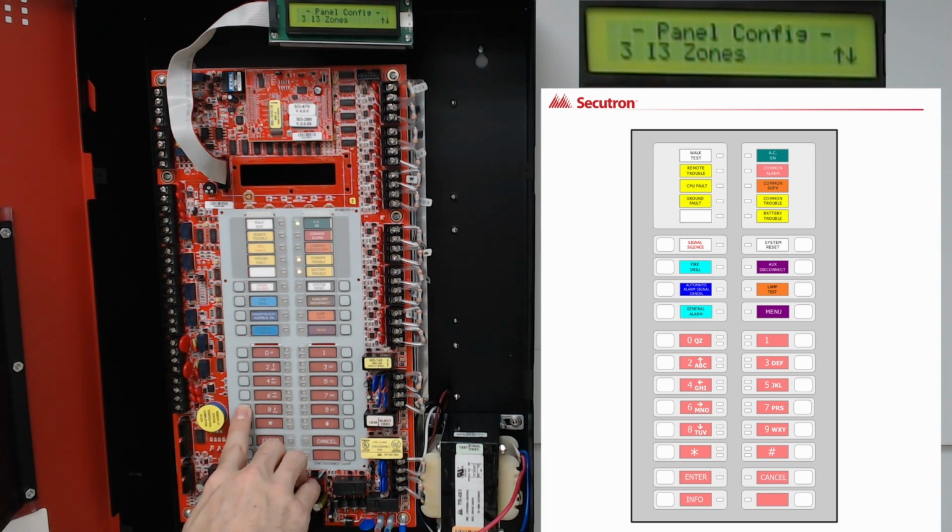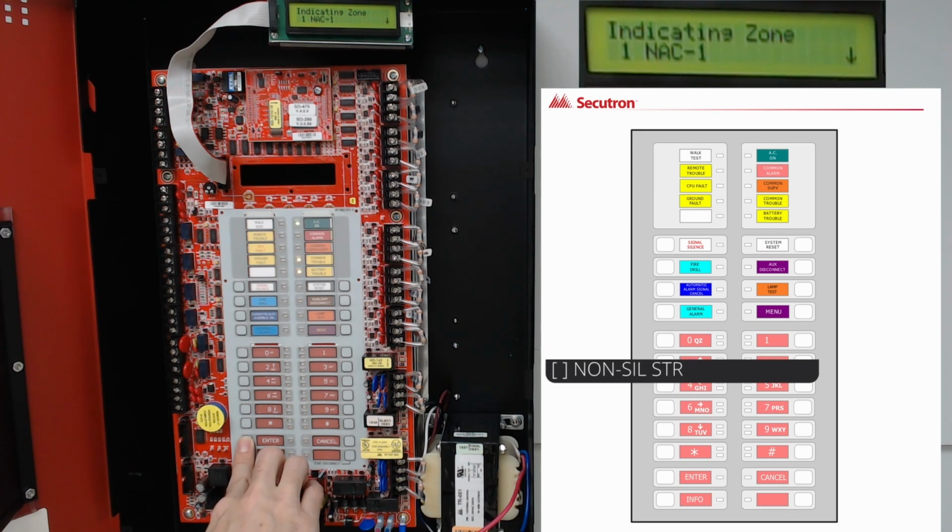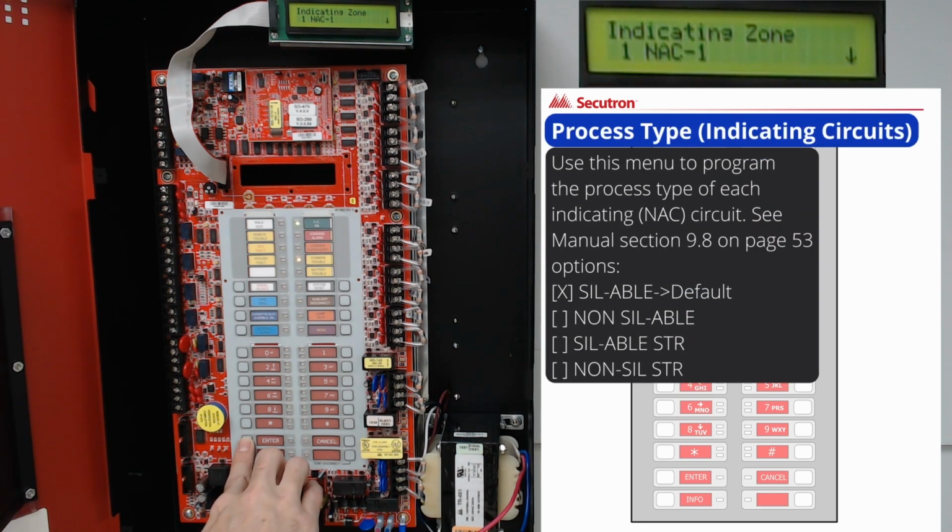Our next option under panel config is output zone. This menu is used to program the process types of indicating circuits. The maximum number of indicating circuits is 4. Only those supported by the particular model are shown in the CFG 300 configuration tool. By pressing enter, we can view the options for our indicating zones. Again, we'll have zones 1 through 4.